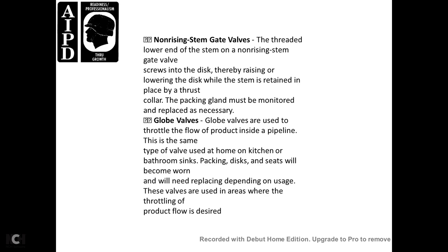Non-rising stem gate valve. The threaded lower end of the stem of the non-rising stem gate valve screws into the disc, thereby raising and lowering the disc while the stem is retained in place by the thrust collar. The packing gland must be monitored and replaced as necessary.